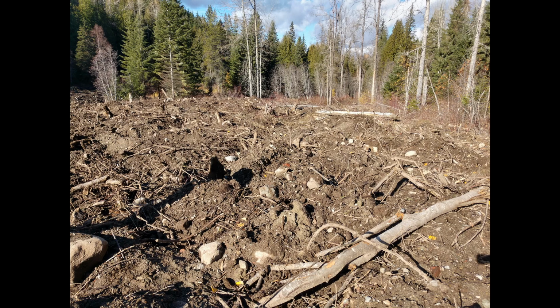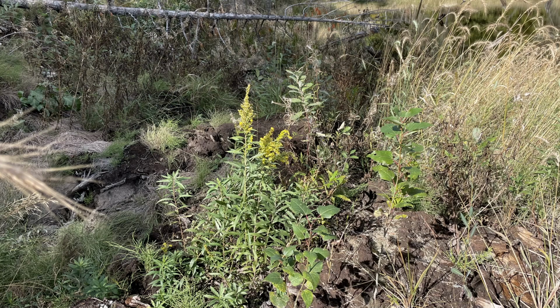The compacted soil on higher ground was prepared for planting using the rough and loosen technique and then covered with woody debris to discourage motor vehicles from driving off the road. The rough and loosen technique really works. These goldenrods, cottonwood trees, and willows naturally germinated on the loosened soil less than 2 years after construction.